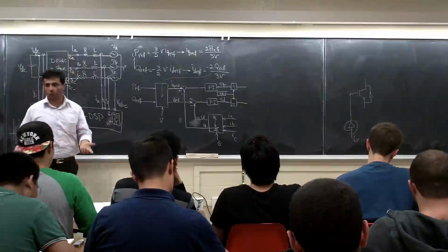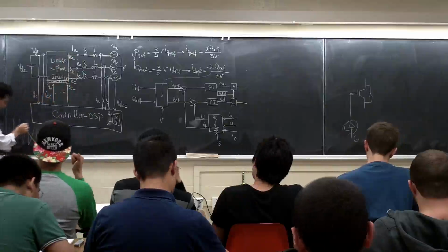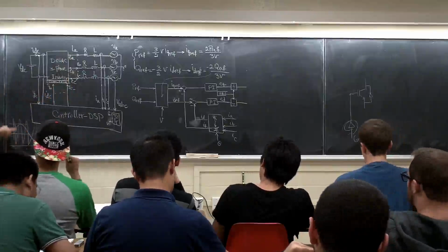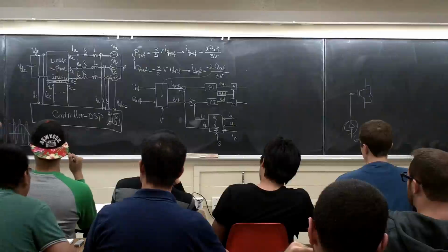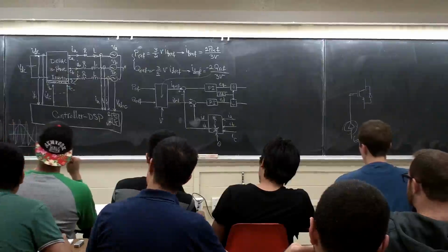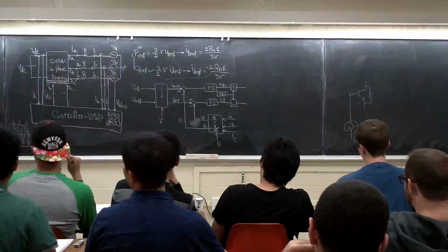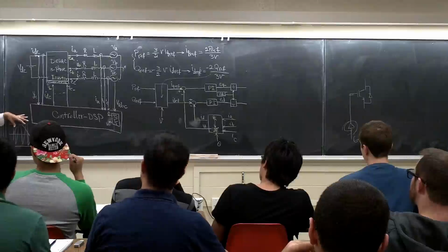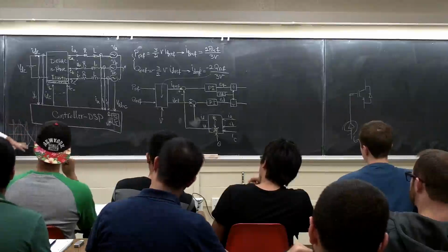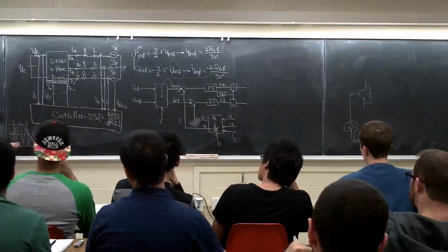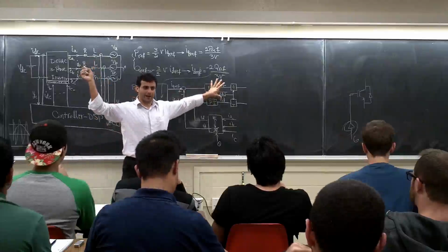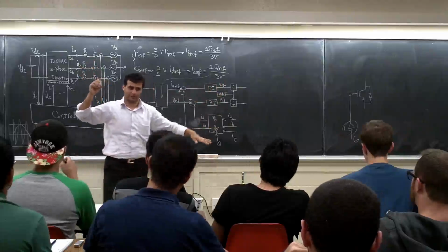But for my control, remember, how much was the peak here? Maximum linear modulation. Anything ring in your brain? One, was it one, right? You guys are young, you should have a better memory. You say the maximum of MA, how much is it? 1, right? So this is a power signal, equivalent to 480 volts, something like that. I divide by VDC to normalize the thing.